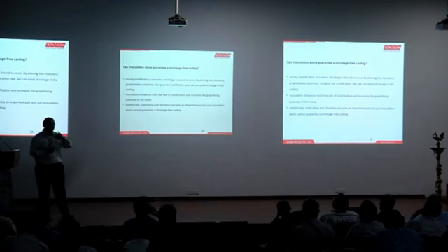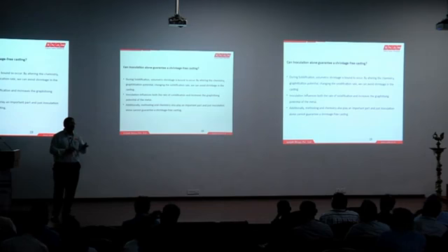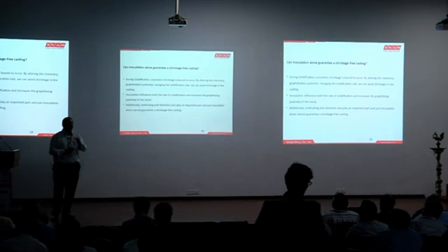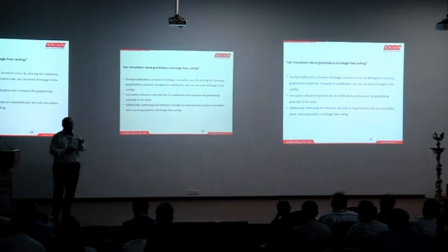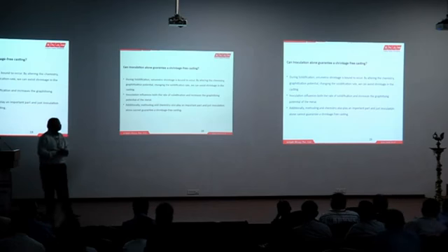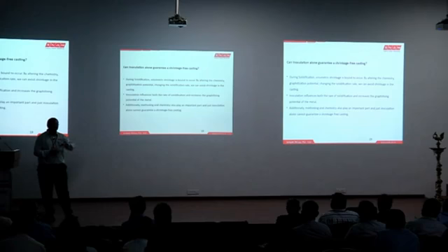So the basic characteristic of shrinkage is that it is a solidification phenomenon. That means a void created where your liquid metal is not potent enough to fill the entire cavity or entire shape of the component within the stipulated time at the given temperature also. So when the rate of solidification is determined by your methoding and chemistry, inoculation supports it. Say for example, any variation coming up in the pouring temperature, or any variation in the carbon equivalent, or any variation in the filling time or heat extraction capability of the mold or the cores or the coating,